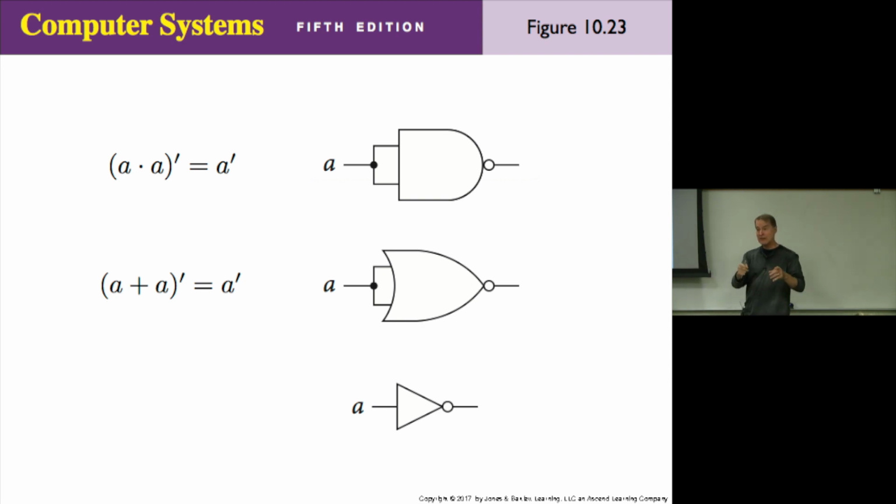Suppose you're in the lab, you have a NAND gate, and you need an inverter. Well, you could plug in a hex inverter, the chip that had six of them on one chip. But suppose you didn't want to plug in a hex inverter. You could take one of your leftover NANDs and hook the inputs together. There's your inverter. Are you with me on that?